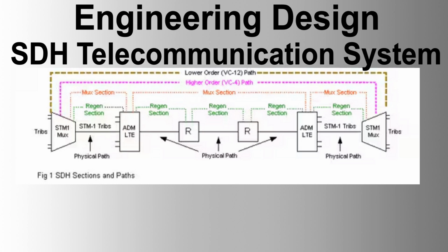SDH system. An SDH-based communication system which will carry all SCADA ICS LANs, ISS systems LAN, as well as voice, video, radio, office LAN systems data using dedicated fibers on the FO backbone. The SDH network shall interface all systems requiring communication between all manned and unmanned stations.